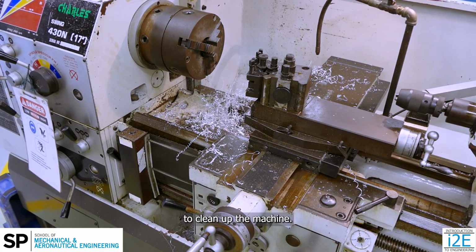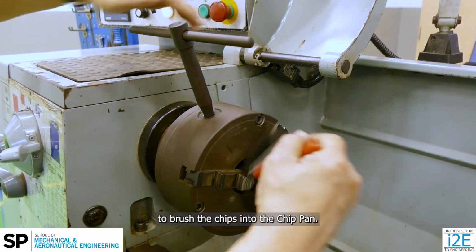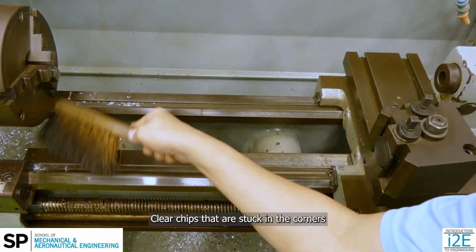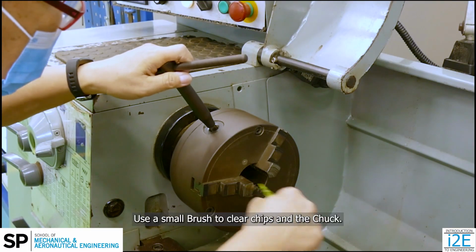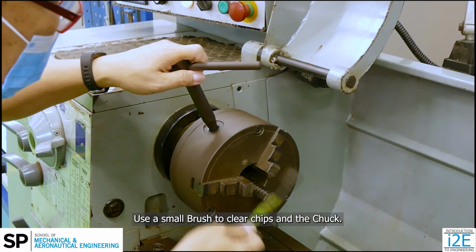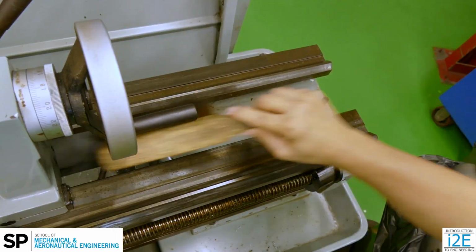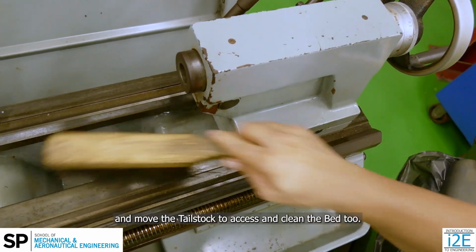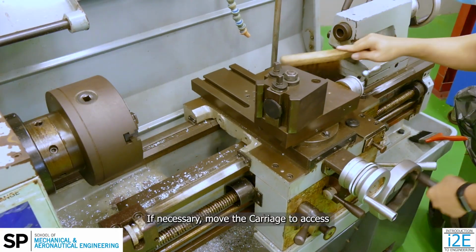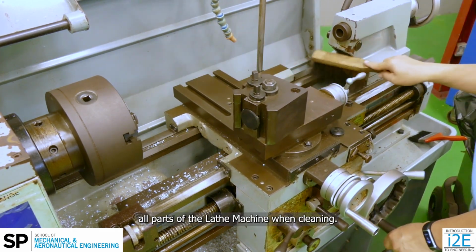To clean up the machine, use the provided brushes and dustpan to brush the chips into the chip pan. Clear chips that are stuck in the corners and grooves of the machine. Use a small brush to clear chips in the chuck. Brush the chips off the splash guard. And move the tailstock to access and clean the bed too. If necessary, move the carriage to access all parts of the lathe machine when cleaning.